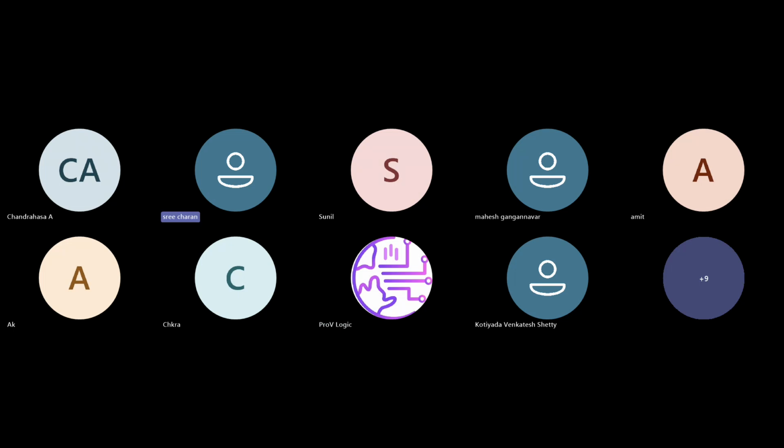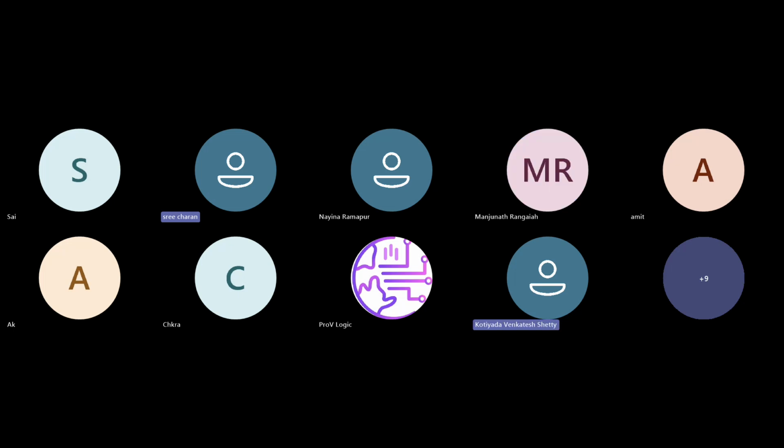I want to know about initialization. I understand the initialization, but my question is that these devices are dual simplex, you told, right? The initialization happens from the physical layer to the transaction layer, right? No. Initially it starts from physical layer to physical layer. It's link initialization. Receiver physical layer to transmitter physical layer to receiver physical layer.